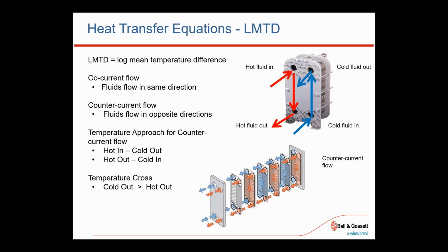I should probably unhide a few of the slides to talk a bit about the log mean temperature difference. Think of it as: the further apart the temperatures are from one side of the heat exchanger versus the other, the better the transfer of energy you're going to have. As they get closer in temperature or you reduce your surface area, your ability to transfer would be greatly diminished.